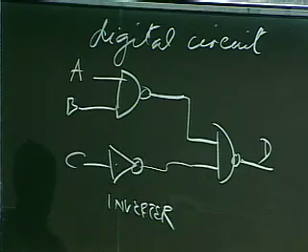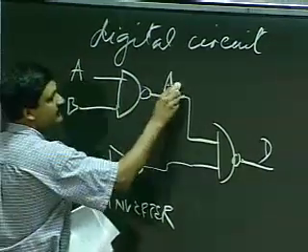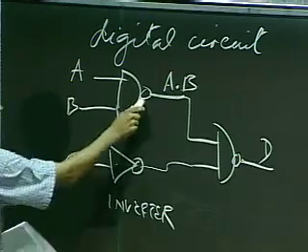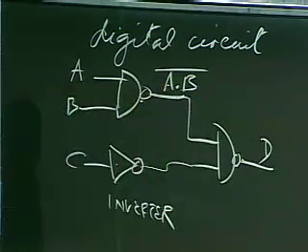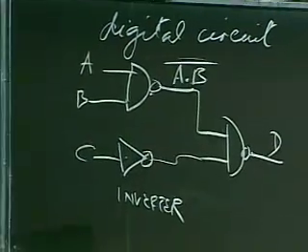Okay? And I can quickly write down what the output looks like using some very simple Boolean algebra, dealing with Boolean values here. So for an AND gate, the output is A and B. Remember, dot is a short form for AND. But there's a negation, inversion. So represent inversions with a bar. So my output is A dot B bar.